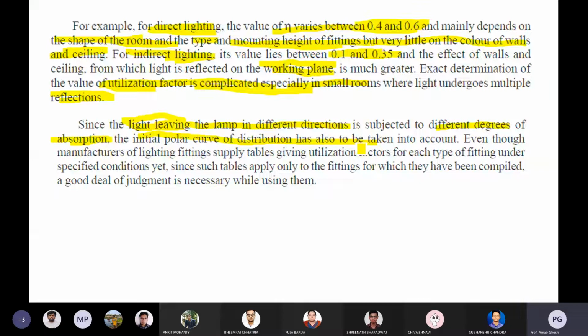If you are going to purchase some specific setup or lamp fittings, you need to know the data sheet of those lamps: how much maximum voltage it can carry. Voltage and current are fine, but the most important thing is how much illumination you are getting from the system, your lumen per meter square. For which purpose are you going to use it? Suppose you have some standard design, is it suitable for multiple sources of light? You need to know that, so you should get an idea of the polar curve.